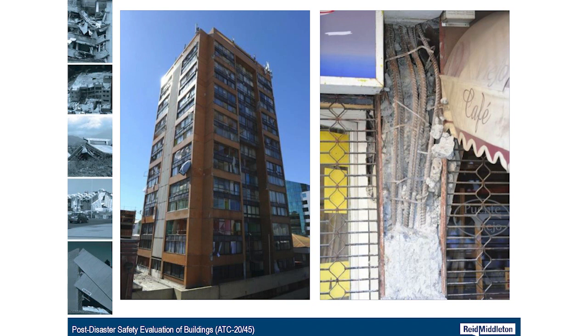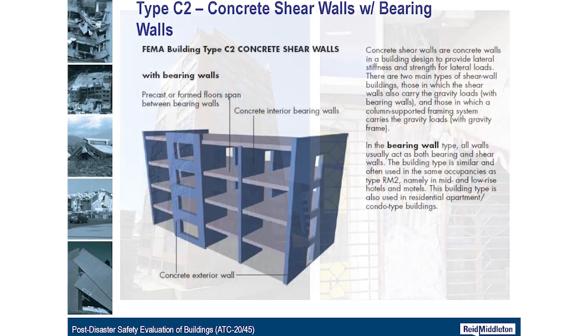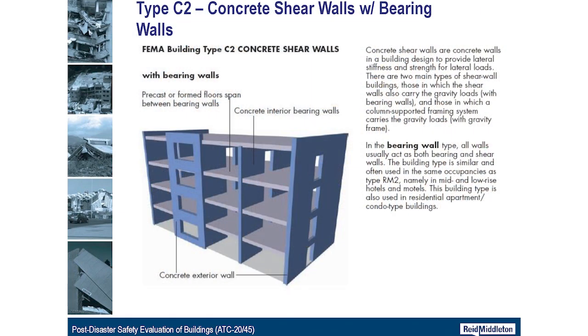mid-rise to high-rise apartment building has rocked back and forth. So in addition to its 24/7 gravity load, there's a ton of extra vertical load that was expected of this column, and due to its limited amount of confinement reinforcement, the confinement ties blew out. Like you put too much load on the pop can, and the pop can blew out, and now those vertical bars have nothing to restrain them, and they're buckling longitudinally. So it's concrete moment frame construction.